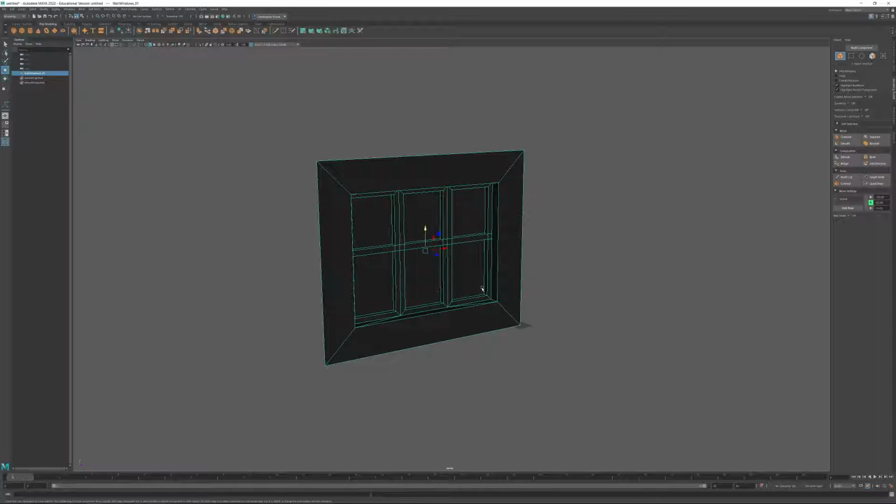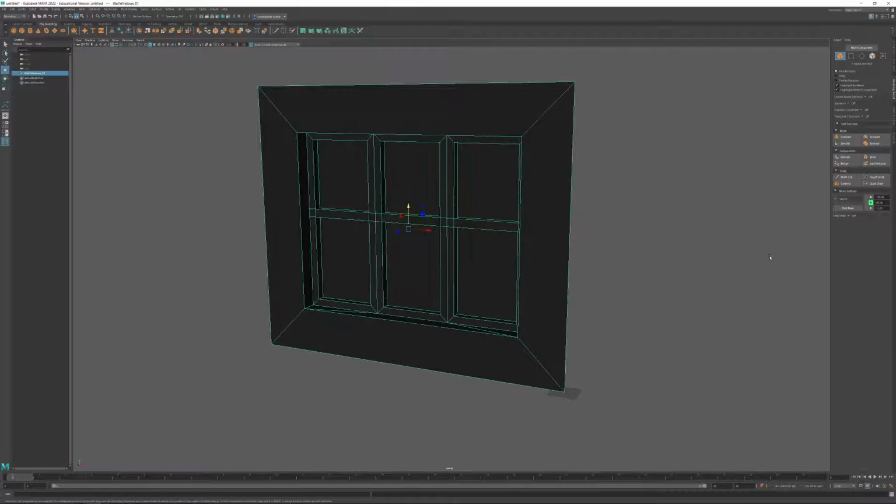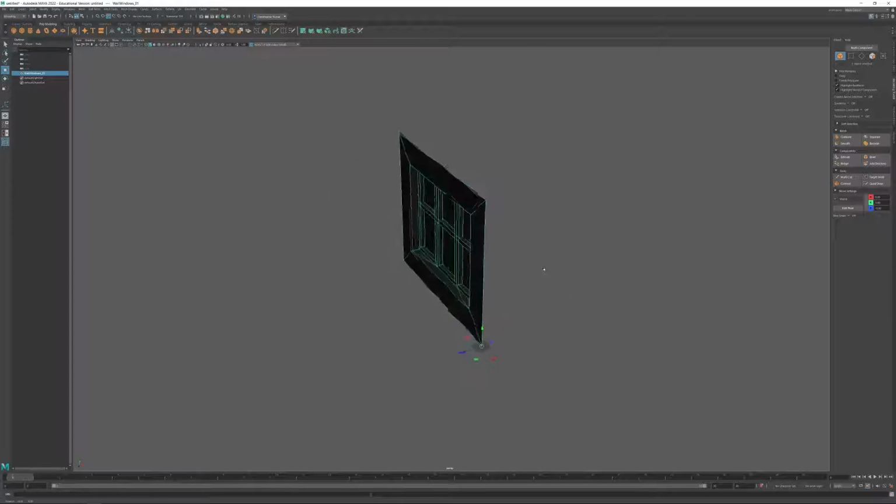This mesh needs to remain at 0, 0, 0 upon export. If you look at where my pivot currently is, it's in the center of the geometry. And we could, if we wanted to, manipulate the pivot and snap it down to 0, 0, 0, like this. We can turn on our vertex snap and snap it there. And now this object actually is rooted in 0, 0, 0.